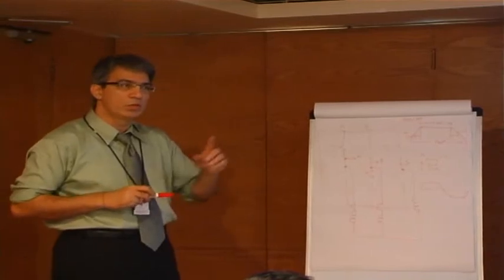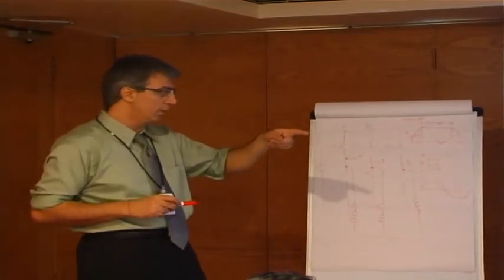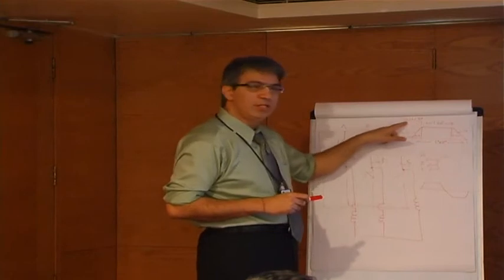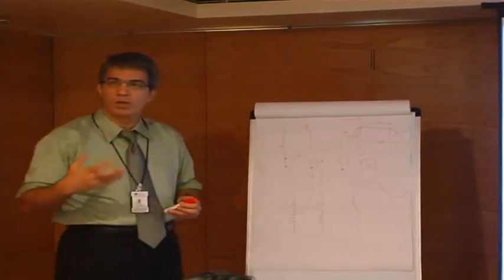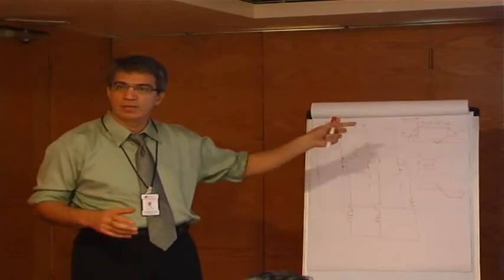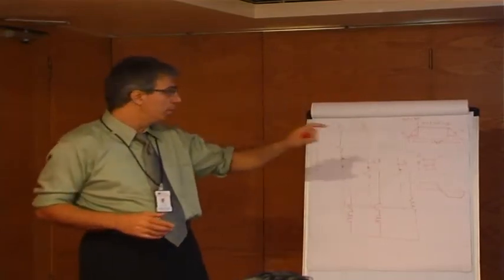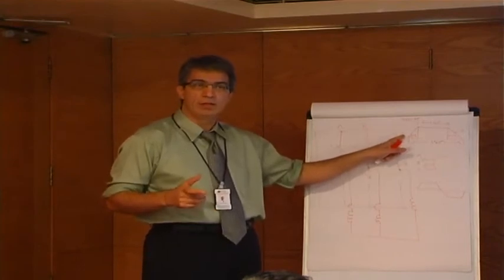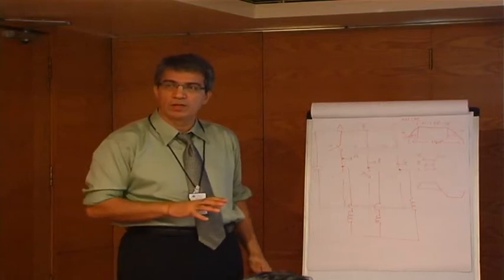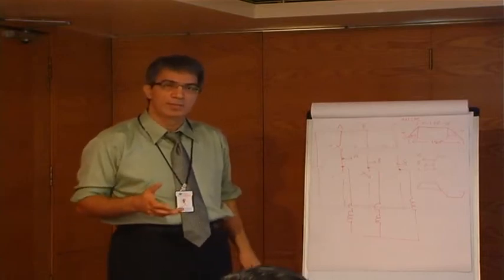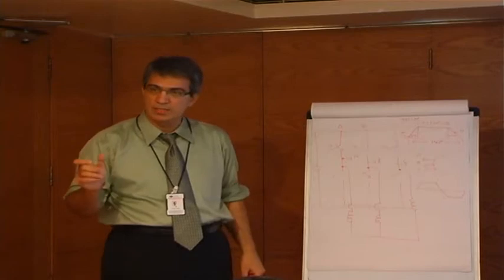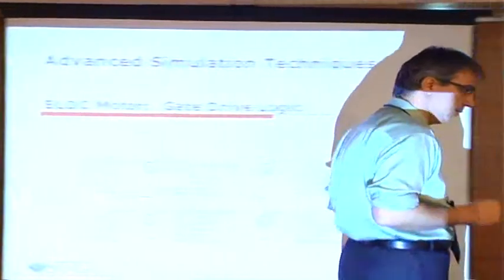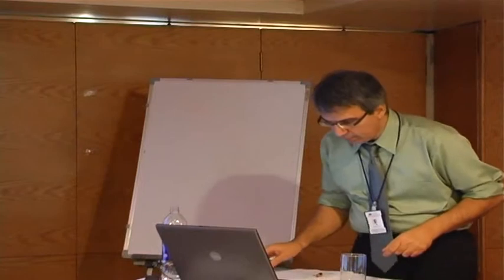Now we will also do an experiment where we change this delay 1 and see what consequences there are when delay 1 is not correct, because it can vary because of manufacturing variations. Especially when you have a low speed drive which you are trying to run with the BLDC, non-geared, then if it's not precise, you have more issues in torque ripple and smoothness.